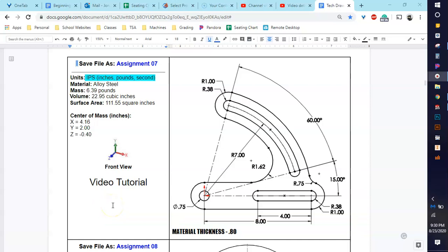When you're drawing this one, you can go about this in several different ways. Some people make this whole entire bottom piece one big slot and then they trim it later on. But I can tell you when you're trimming slots, sometimes it messes up all of your defined relations. When you do a slot, it doesn't actually say that this is tangent, that's tangent.